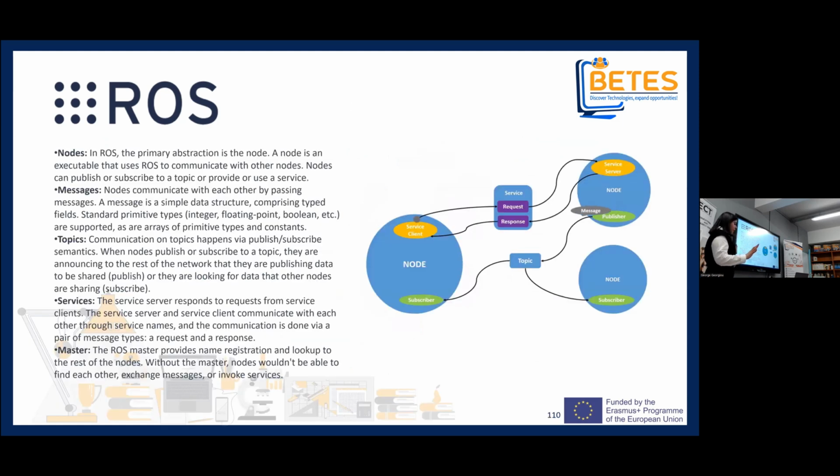And I will try to explain a bit of the concepts that are used in ROS. They are the nodes, the messages, the topics, and the services. The nodes communicate with other nodes, and they perform a computation. Nodes can communicate by passing messages.